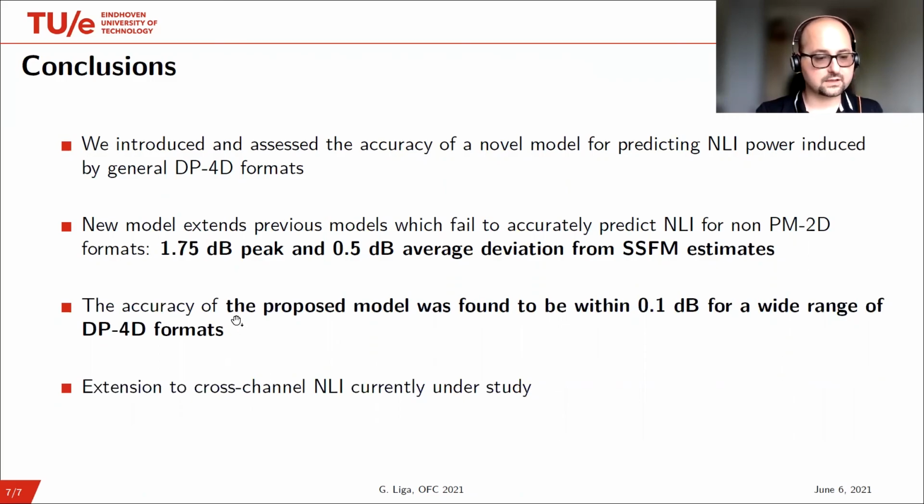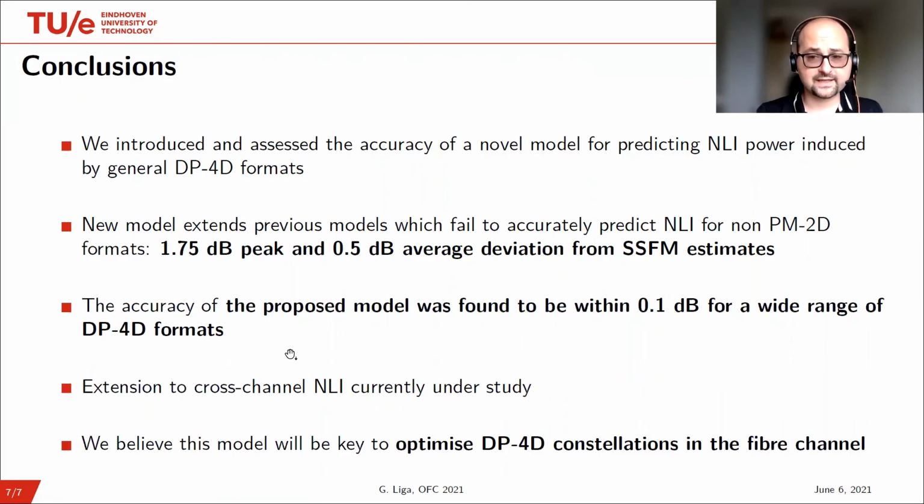Extensions of this model to cross-channel nonlinear interference terms is currently under study, as we only provided a formula for the self-channel interference component. And finally, we believe that this model will be a key tool to optimize dual polarization 4D constellations in the optical fiber channel.